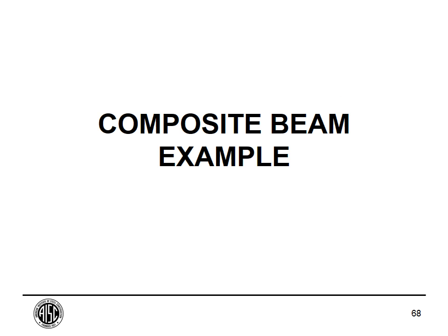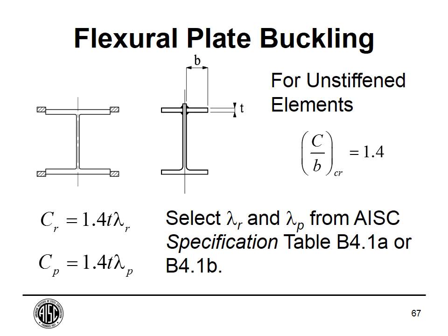Now that's obviously if you want to stitch weld this member. Obviously, you don't need to check this if you don't stitch weld this plate to the web, or stitch weld this ear plate, or whatever we called it last time, to the column flange.